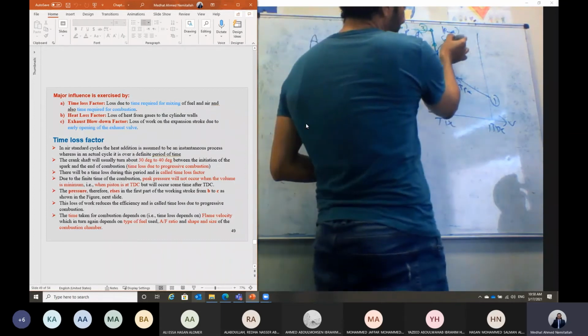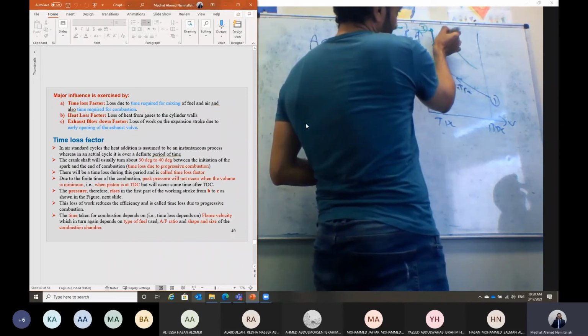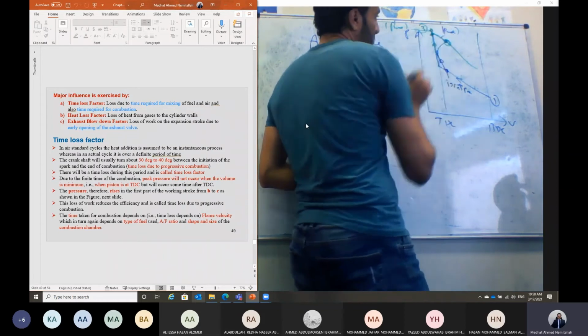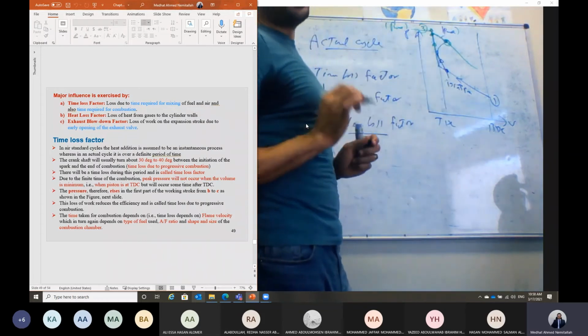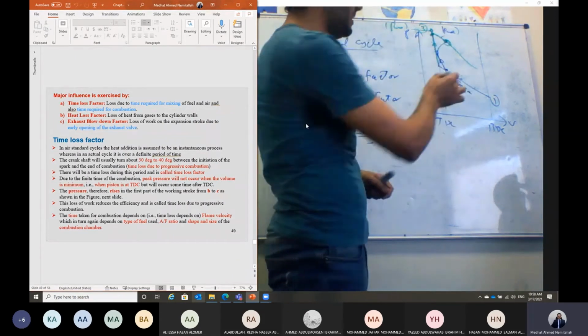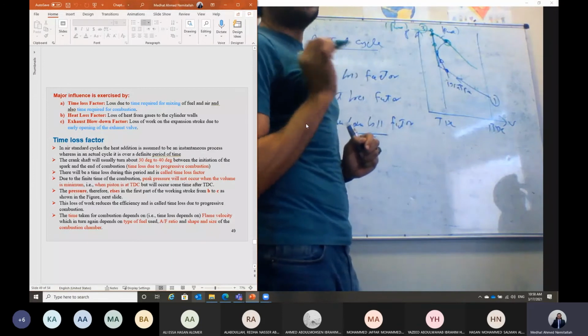And then we can have the expansion. If this expansion is isentropic, it should approach a point less than point 3 here. But it is not isentropic. But here, Shabab, we see the area on the PV diagram. The area contained by the cycle should be representing what? The net work.